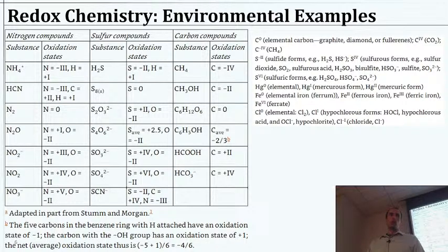On the flip side, sometimes we want to get rid of chlorine before we discharge, let's say, an Olympic swimming pool. There's a lot of chlorine in there, and it's like 1 million gallons. If we discharge that within 1 hour, it's like 1 million gallons per hour of flow, so that's actually quite a large flow rate with quite a lot of chlorine. It represents a very large hazard for the environment, so we might have to add a bunch of sulfide or thiosulfate, or something that's a reduced version of sulfur, to consume that chlorine.